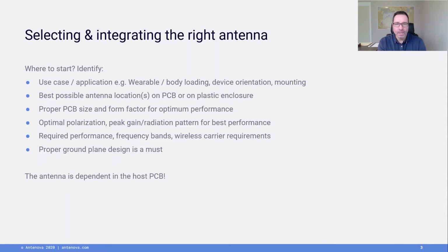What will be the orientation? How will it be mounted? What is the very best position for the antenna or the antennas on your PCB or within the enclosure? You must identify the proper PCB size for the antenna, the form factor for optimum performance.